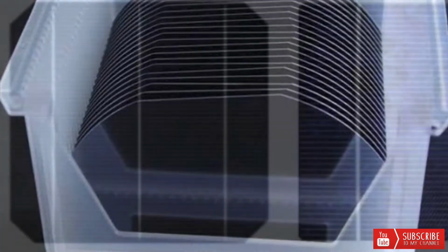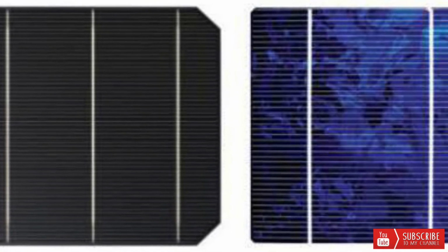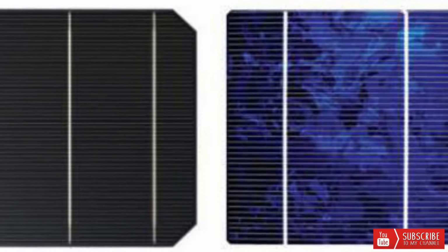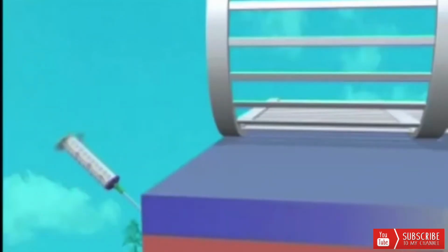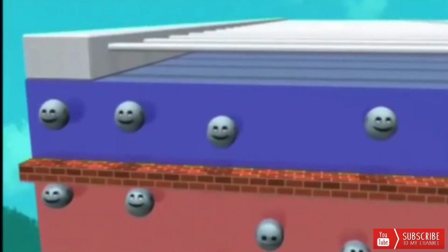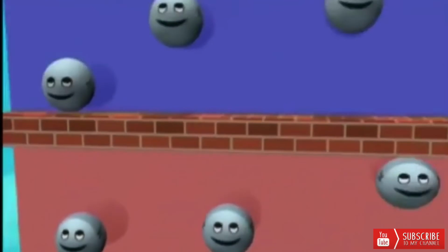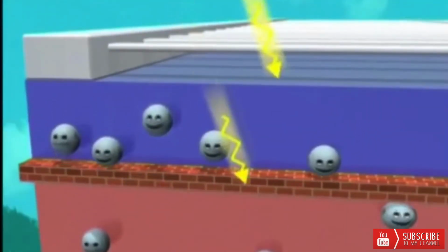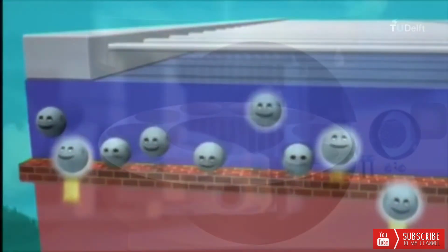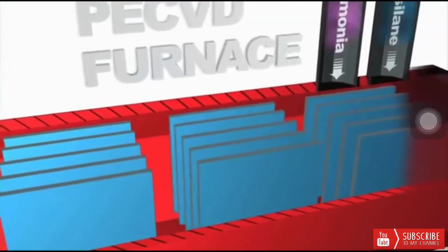The following processes will convert a wafer into a solar panel capable of converting solar power into electricity. In an oven-like chamber, phosphorus is being diffused in a thin layer over the surface of wafers. This will charge the surface with negative electrical orientation. The combination of boron and phosphorus will cause a p-n junction, which is critical for the proper function of a photovoltaic cell. Because pure silicon is shiny, it can reflect the sunlight.